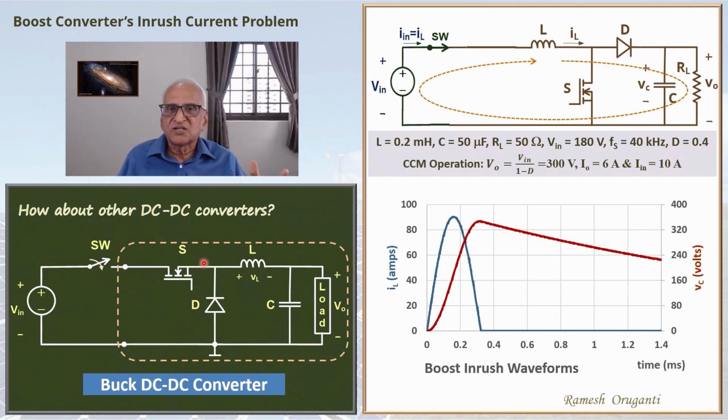That's called soft start, in order to build up the current and voltage on the output side slowly. So that's not an issue. In the case of boost converter, the switch is on the shunt path. In the case of buck converter, the switch is on the series path on the input side. So we have all the control we need to limit the current. If the current becomes too high, we can switch off the switch, yes.